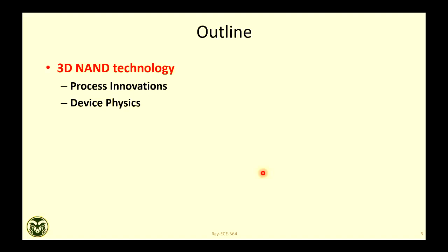Now it is more like a workhorse for industry, the 3D NAND, right? It is increasingly replacing hard disk drive in a data center, right? 3D NAND is more like number of layers, in a three-dimensional building. The more layers you can grow, the more bit density you can have. So that is still not going to its end yet. It is still, I'll say, the middle phase of the technology development. Whereas hard disk drive, and DRAM, their scaling has been saturating. But 3D NAND keeps going, every 2 years almost doubling the density. So that's interesting and very important as well.